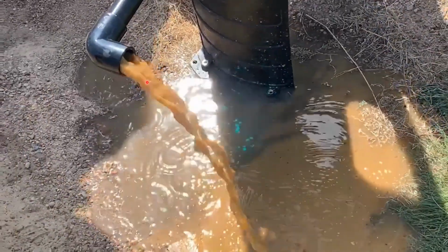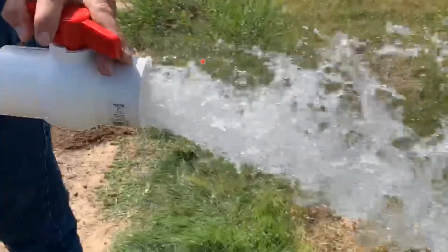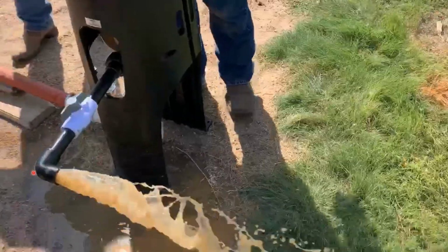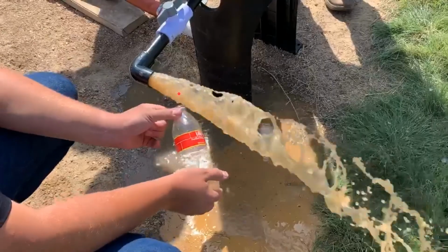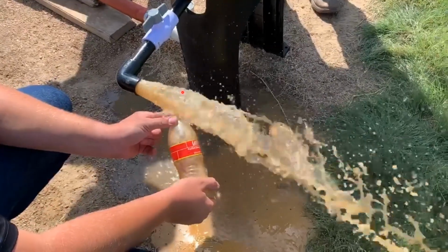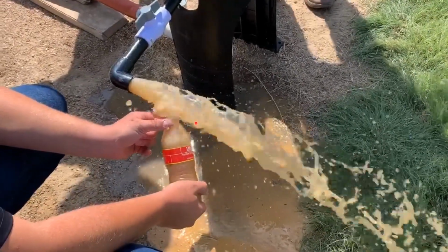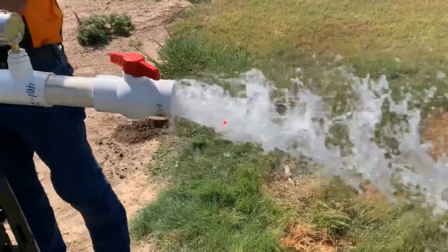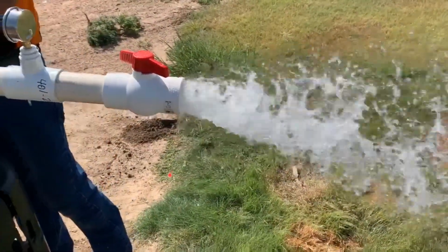We have an automatic valve here. Now he's backed the pressure off to 3 psi across this in terms of loss. And so now we're getting adequate flushing. He's taking a sample of those purge water. We'll end up taking a sample of this clear water. And that's actually what we use for our standards.